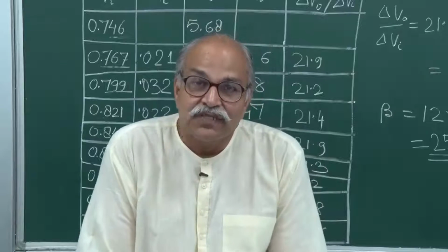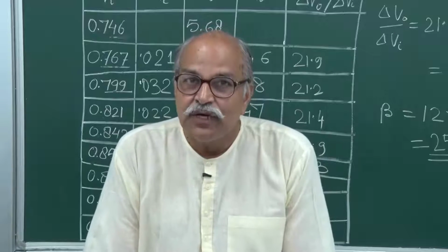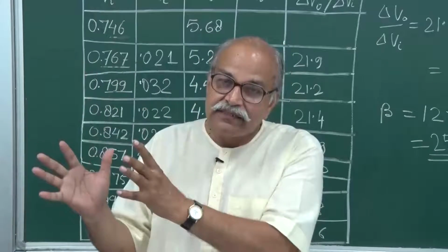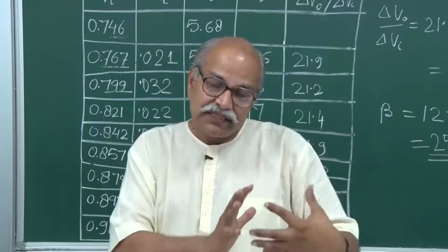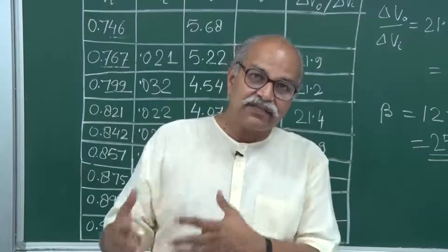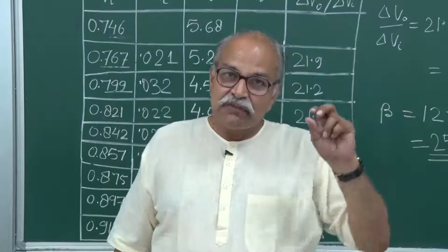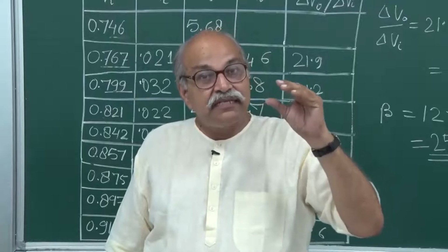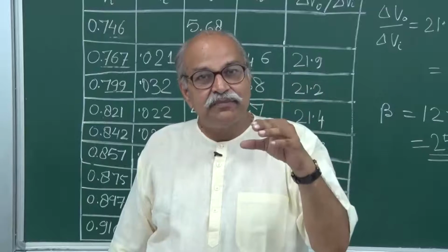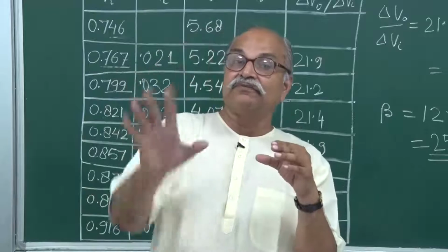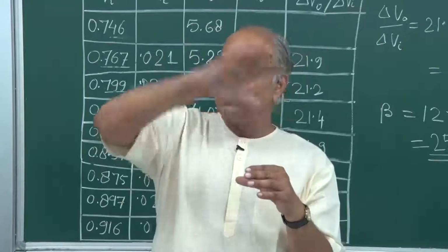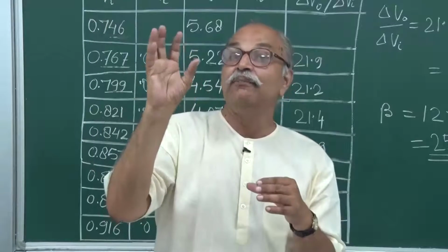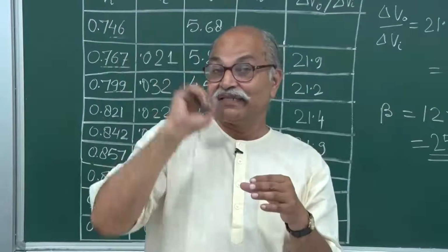So when we use a transistor as a switch, what we do is we control this output circuit through this input. You have already seen the cutoff region and the saturation region. So if somehow I decrease my VBB, the biasing voltage that I am applying on the input side, the transistor will go in the cutoff region. In the cutoff region, there are no currents anywhere, and at the output you have the full battery voltage VCC that appears there.